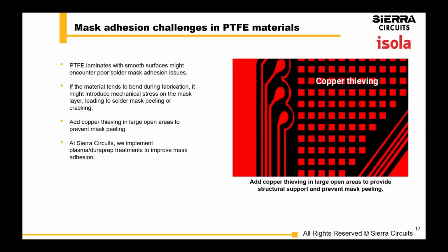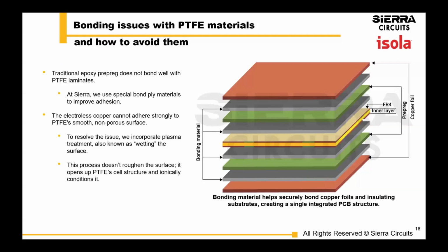Now, it's not always possible with your RF designs, but wherever you can properly add copper for better solder mask adhesion, that would be great. It also helps with etching, and that of course will help with your impedance requirements.